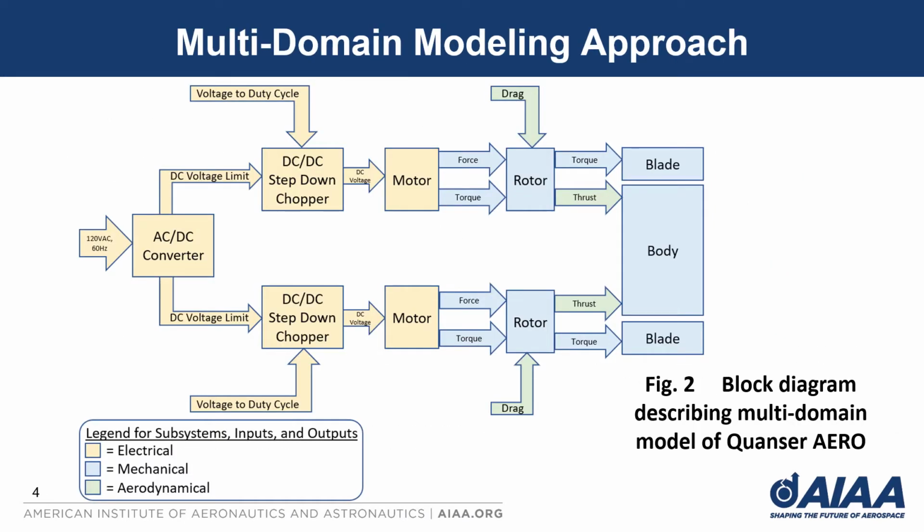This diagram gives a top-level overview of the multi-domain model being optimized in this work. The model was developed in Dymola using the Modelica modeling language. Modelica allows for the implementation of models that have components from multiple engineering domains by defining equation-based interfaces between components that adhere to the principles and laws that govern those domains. The model developed for this work integrates electrical, mechanical, as well as aerodynamical components and interfaces to create a more complete picture of the system that's being modeled and its dynamics.